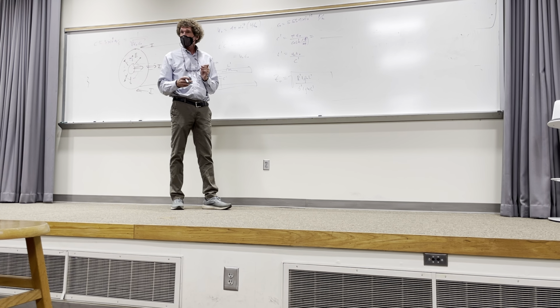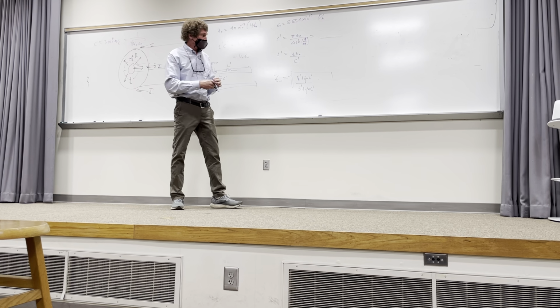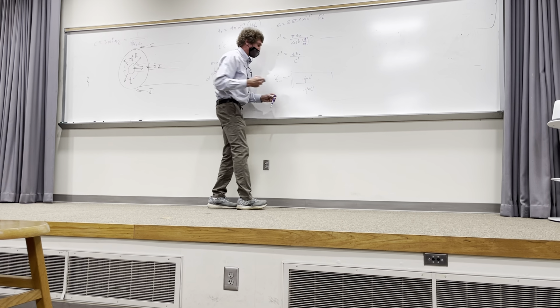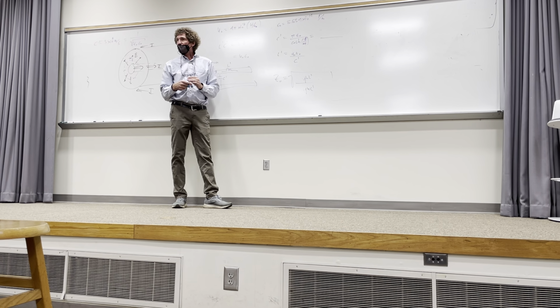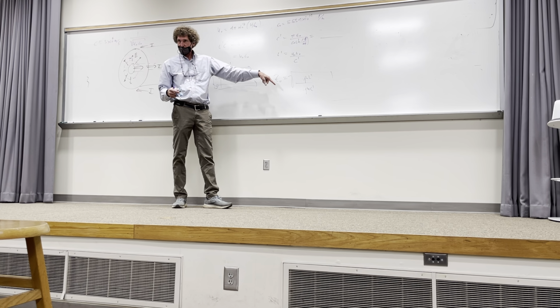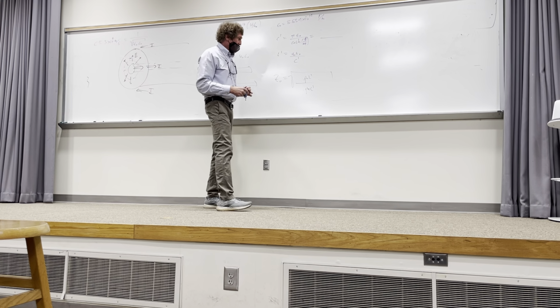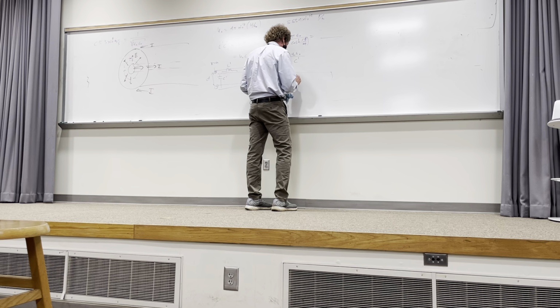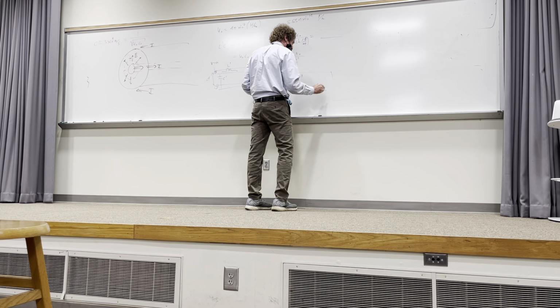Do y'all follow me? It's stated in the problem both R and G are 0. So I make R and G 0 by erasing them. And one thing that's very apparent is what? The j omegas cancel for a lossless case. Follow me? So when that happens, I'm really left with just the square root of L prime over C prime.